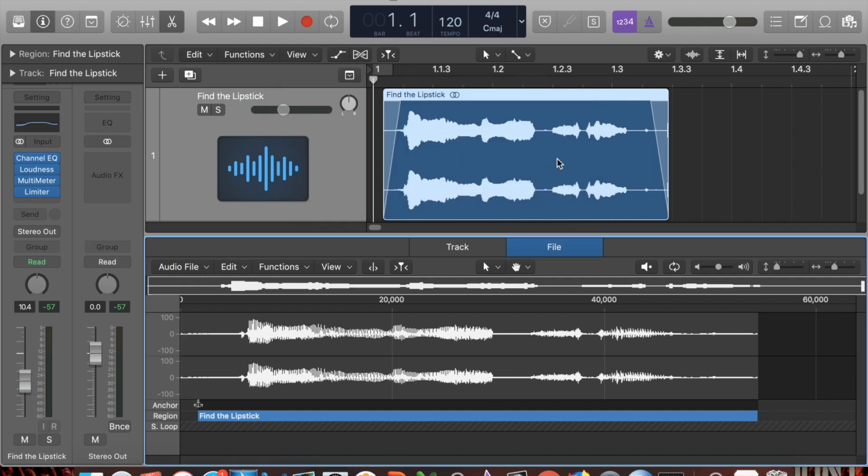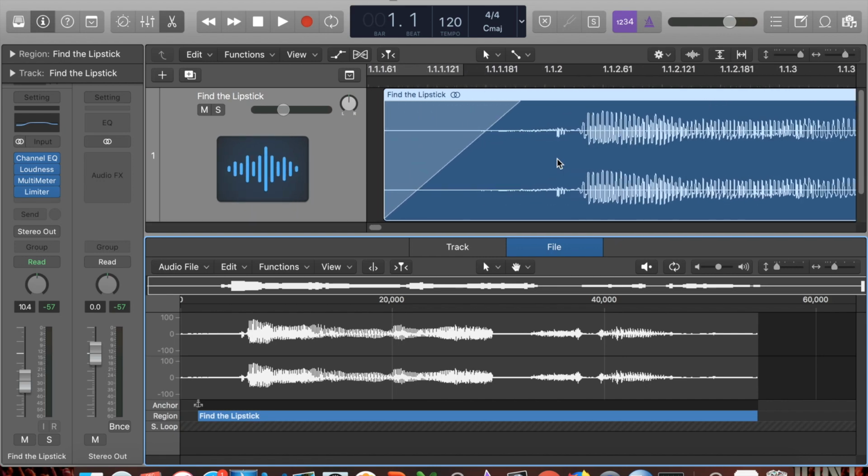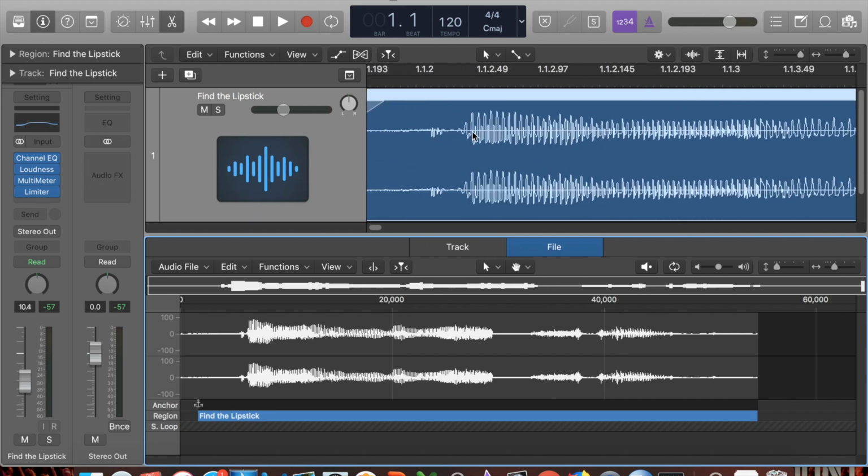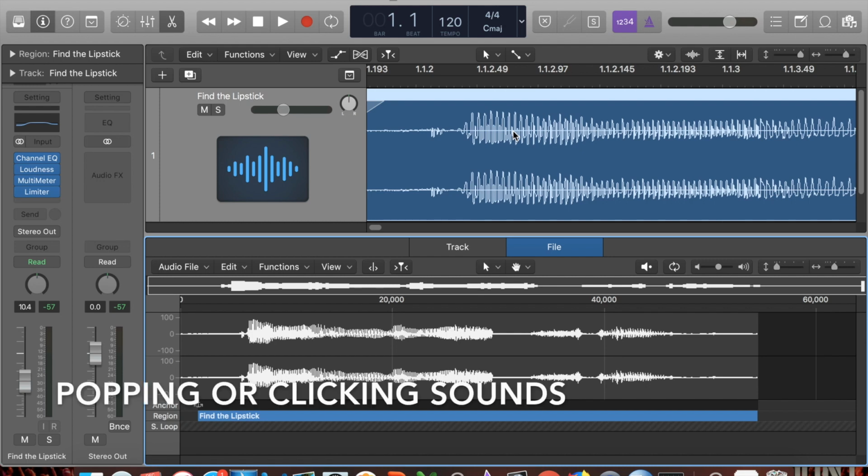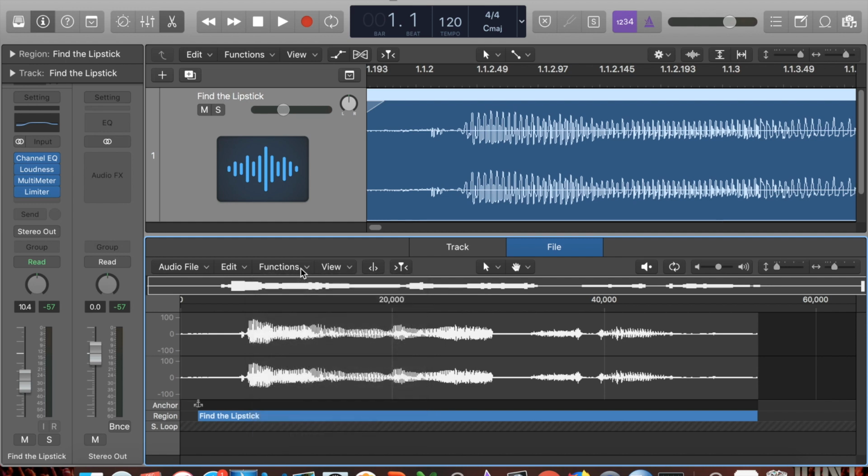And what that means is basically from this line, which is your direct current, this line right in the middle. Sometimes this whole waveform can be shifted up just a little bit, and that can cause things to sound a little funky. So if you do hear that audibly, then it is a good idea to remove the DC offset. Just as a precautionary measure, I think it's a good habit.